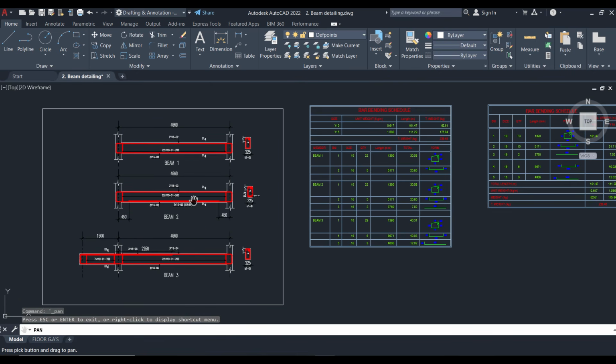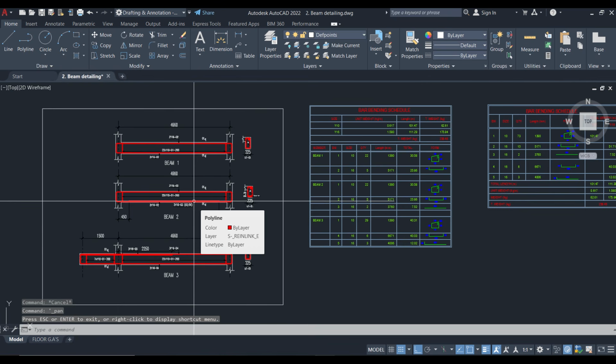You can follow the template of what we have in BS 4466. This is the standard as prescribed, but in practice, in order to make work simpler for engineers, you can also use this method to prepare your bar bending schedule. The idea is, number one, to give the size and shape of reinforcement to help your iron benders where they are cutting the shape of reinforcement. Number two, in order to calculate the quantity of reinforcement, for you to quantify the reinforcement effectively with reduced error.